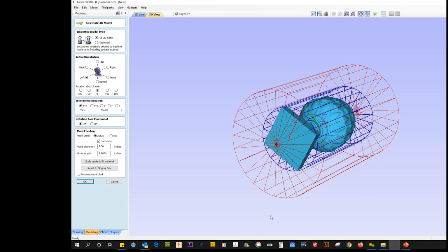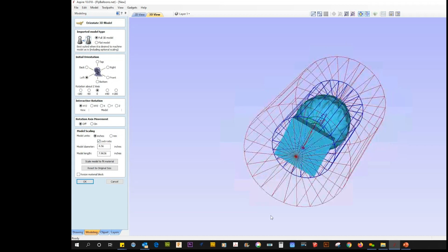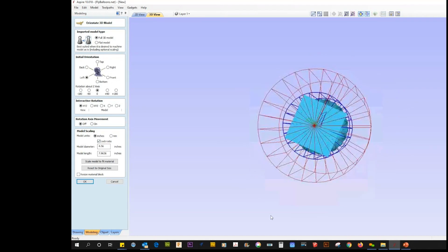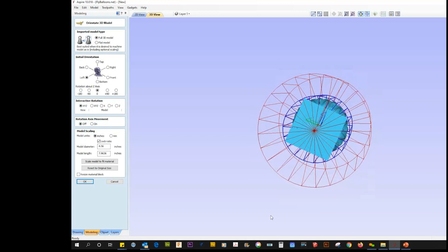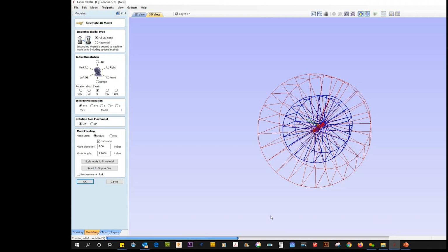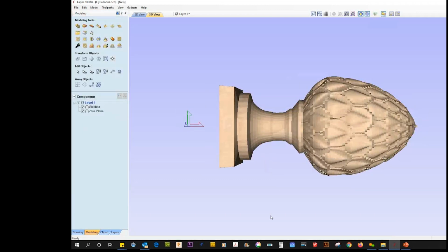As the material is carved in the roughing, it will take into consideration those highest points, and it will automatically cut off all that and go down into the rough area of the stock to start carving the model. You should not have any air cuts. But from there, we would say okay. And here we have the design.